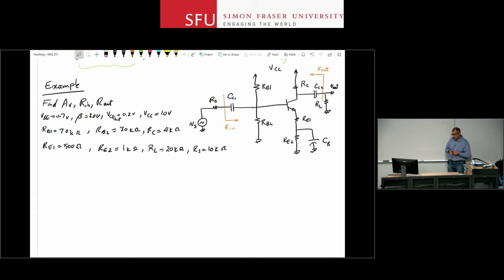So once you see that, you can always go back to the small signal model for the transistor and solve the circuit at DC and then use the small signal circuit to figure out all the parameters that you need. However, if you know your circuit theory, if you know your stages well, you can use the analysis that we have already performed in order to solve the circuit. And I'm going to show you that. But I highly encourage you to do the small signal analysis in a proper way after you do the DC analysis. And just convince yourself that the results will be the same.